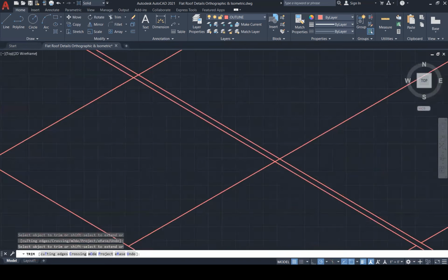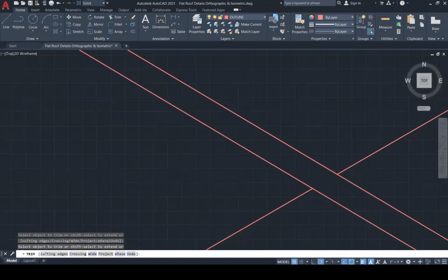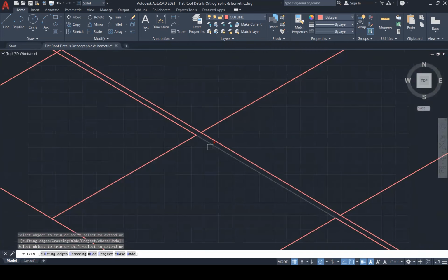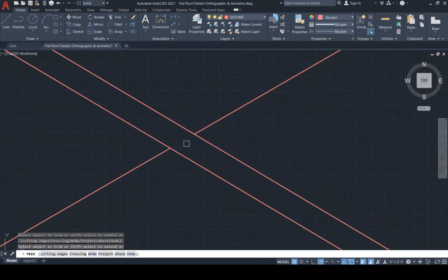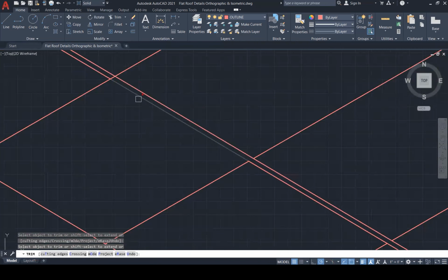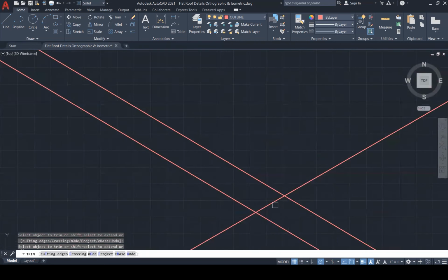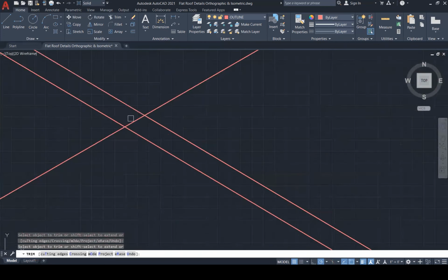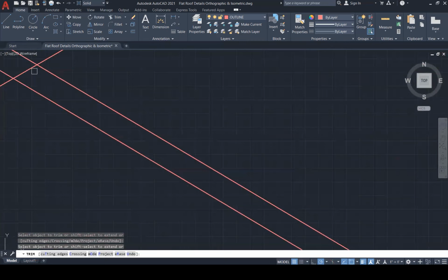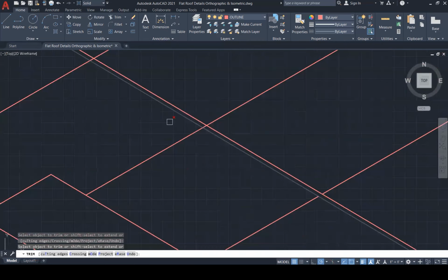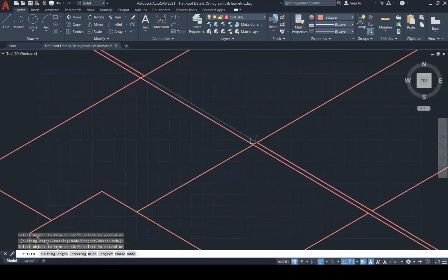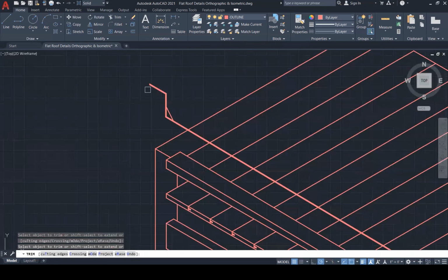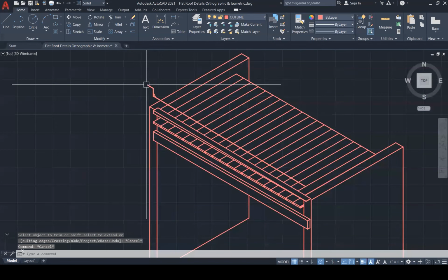So this is the last material that is added to the roof. And this is also the material that takes on the weather. So the sun shines onto this felt and the rain falls onto this felt. So both the rain and the sun actually go onto this material. So this material is what protects the roof from getting the moisture and from getting any rain coming inside. Very important. Built-up felt. Remember it. All right. Good.